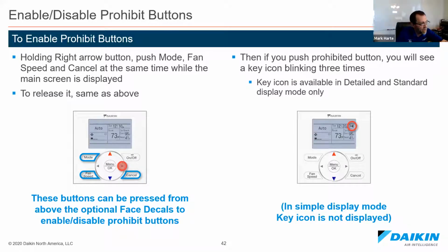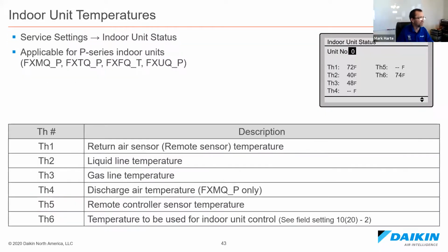And every time they hit a button, whatever, and you can select what buttons you want to lock out. You don't have to lock out everything. And on the right, you'll see that little red circle with that lock symbol, or that key, excuse me. When they try and change something that's locked out, that key will pop up. You can make it so that key doesn't show up, so they don't know why it's doing it. So a lot of things you can do with the nav controller.